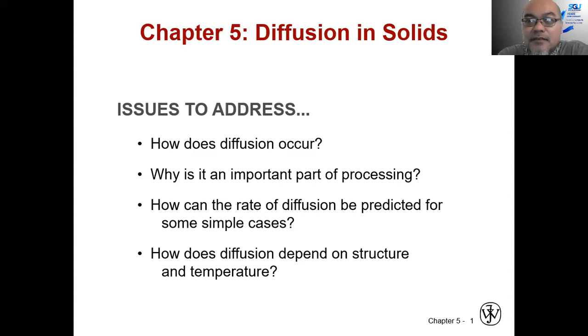When we want to make a solution, a solid solution, a metal alloy for example, the impurities or the solute cannot just be directly spread all across the volume of the host material. Usually they have to be introduced at the surface, and then slowly they will penetrate into the depth of the material. And this penetration is done using the process of diffusion in solids.